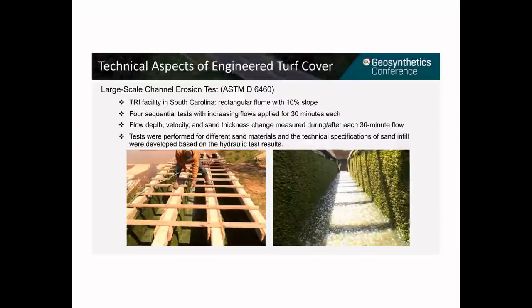Large-scale channel erosion test was also conducted at the same TRI facility. The test was conducted in a rectangular flume with sequential tests and increasing flows. The flow depth, velocity, and sand thickness change were measured during testing. Tests were performed for different sand materials, and the technical specifications of sand infill were developed based on the hydraulic test results. The photos at the bottom show the hydraulic flume and water flowing over the engineered turf cover during testing.